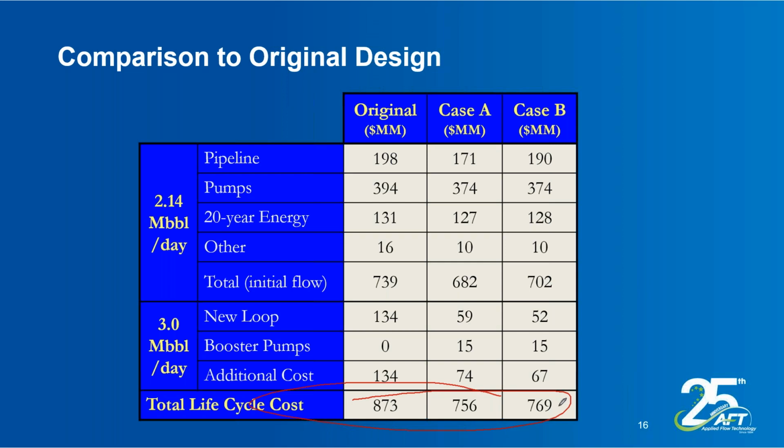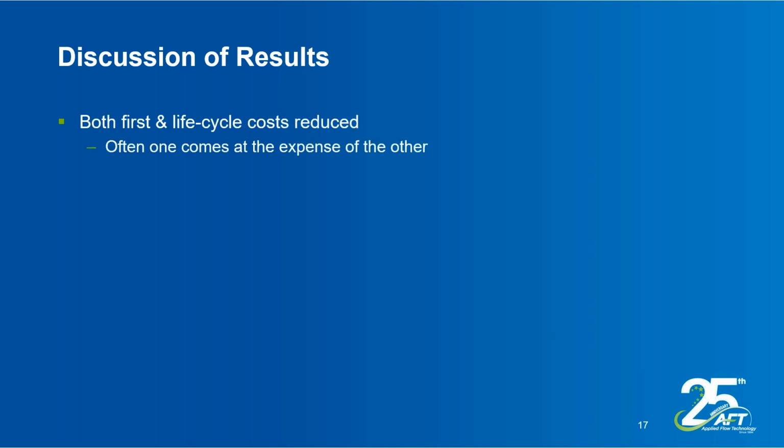Imagine if you're able to allow a little bit more flexibility where maybe the parallel flow path could have been a different diameter. That could have been used to experience even more significant savings. Yes, it would require maybe a different pipe size in that parallel loop, but you could save more money though. Those are all much easier to look at when you have an automated sizing tool that can look at all the different cases for you automatically.